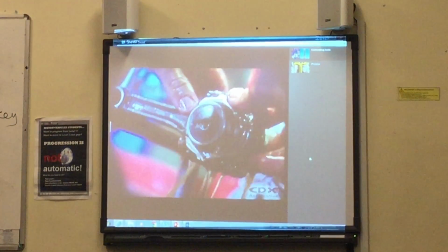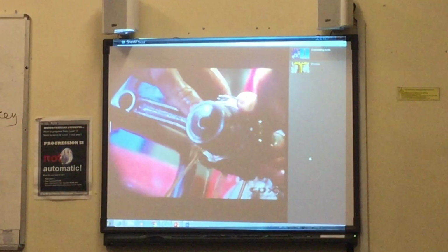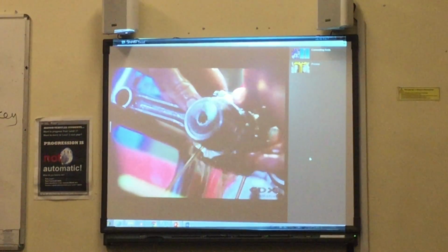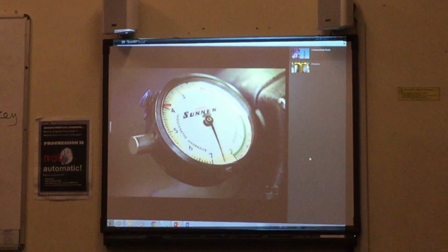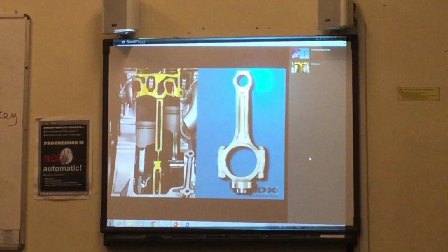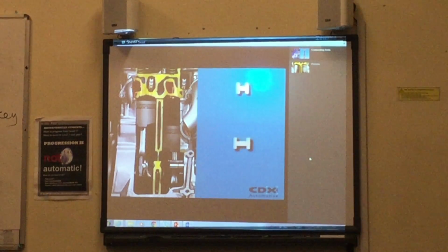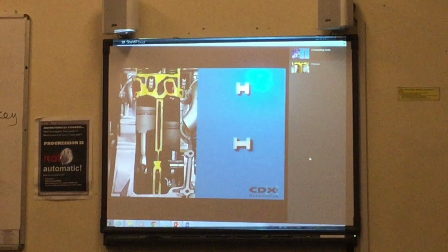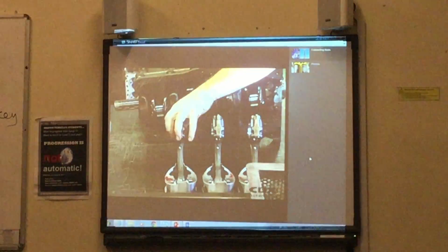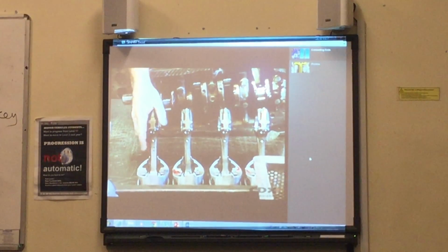Connecting rods must be very strong and rigid, and as light as possible. They are subject to stretching, compressing, and bending, so they are highly stressed. They are cast or forged to form an H near the small end and an I near the big end. This shape provides greater strength to resist the stresses than a solid rod of the same mass. To maintain engine balance, all the connecting rods in an engine are a matched set.